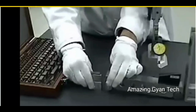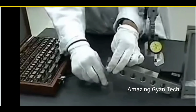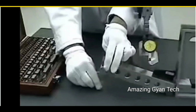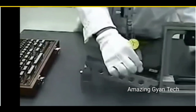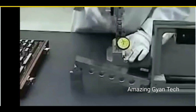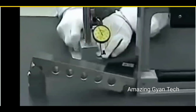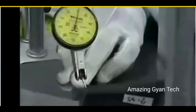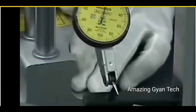So again he has used the new slip gauges and he is putting the sine bar once again on the slip gauge, and he is trying to make sure that the surface is showing 0. Again he will dial and ensure it is showing 0. Until it shows 0, you can't do any calculation. When it is at 0, we need to calculate the slip gauge thickness we have added, and using that we can calculate the angle.